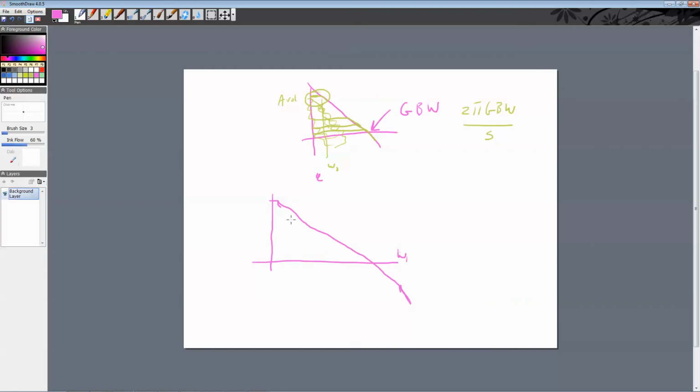So that's omega 1, that can be omega 2, and you can come up with the transfer function of that. The thing is that the gain bandwidth is in here, and that'll tell you from the data sheet where it's 0, so you can still figure out that yes, I can design in this space. And you might think, well, that pole is so far out of our frequency regime that it doesn't matter.